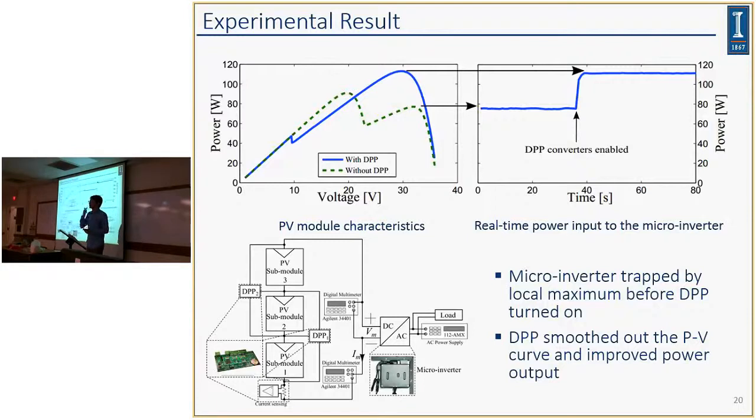So you're really getting the power that's going away. Like you're operating a little bit above that, but it's going directly to the DPP. Is that correct? Sorry, what do you mean? So the dip is due to them turning on. You have losses. Yeah, I'm using a linear regulator to power the gate driver, so it's probably not very efficient. And it's right before the microinverter, picking up the DPP power. Yes, the DPP actually draws power from the panel.